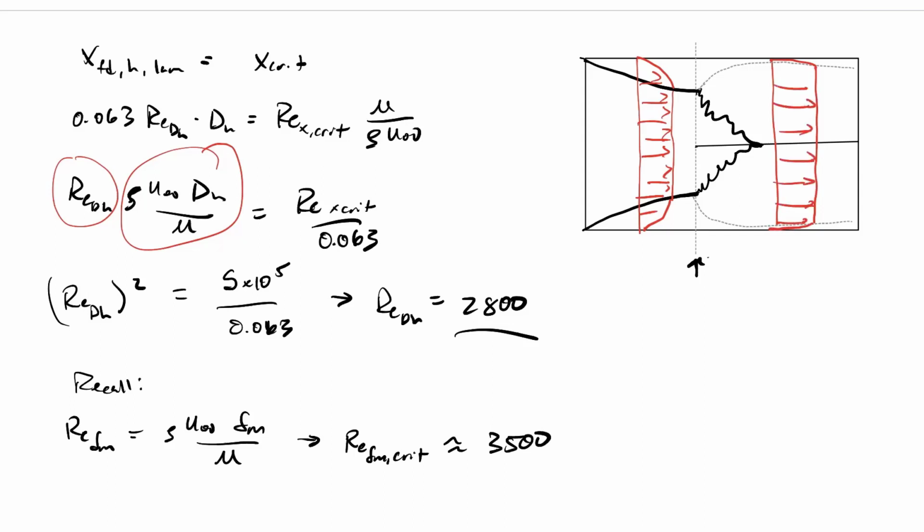Away from that viscous sublayer, if you take the time average velocity at any point, it's basically constant. As you continue in this positive X direction, that velocity profile is not going to change, because we're not changing anything about the average boundary layer thickness as we go. We're not changing shear stress profiles as we go. There's chaos due to the turbulence, but it remains constant. Does the viscous sublayer not grow in X?